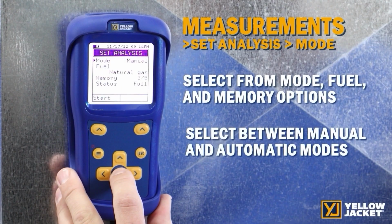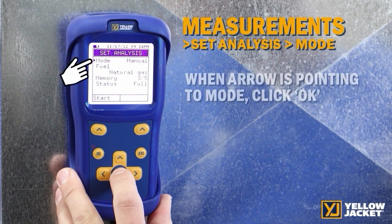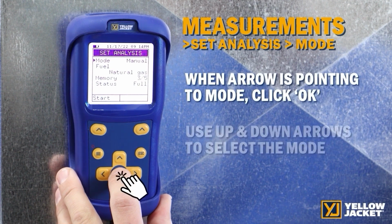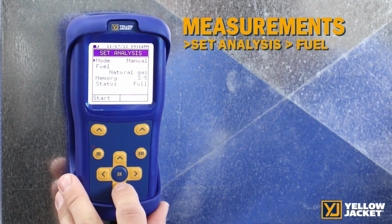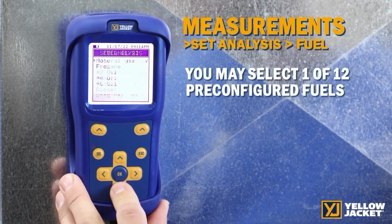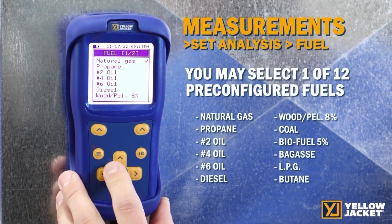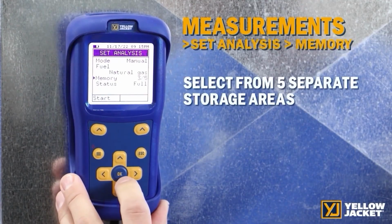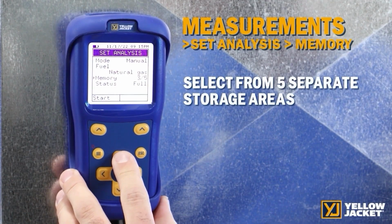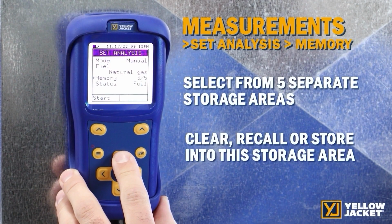You may select between manual and automatic modes. When the arrow is pointing to mode, click OK and then use the up and down arrows to select the mode. In the fuel menu, you have the option to select one of 12 preconfigured fuels. Memory allows you to select which of the 5 storage areas you would like to be in. You may clear, recall, or store into this storage area.